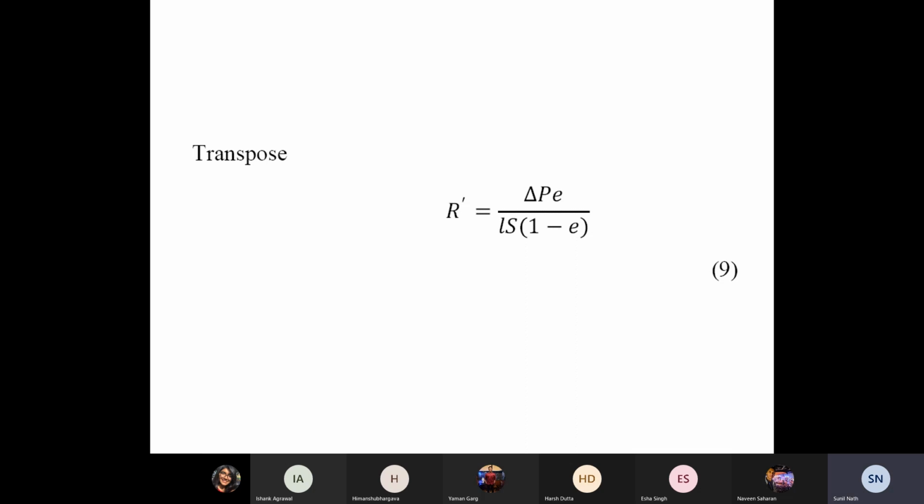Now, if you remember, I had defined two average velocities. One was the superficial velocity and the other was the average velocity through the packed bed. For the velocity through the packed bed, we gave the subscript 1, so it was U1. And this U1 was nothing but the superficial velocity u divided by epsilon, or divided by e. So u1 was u by e.